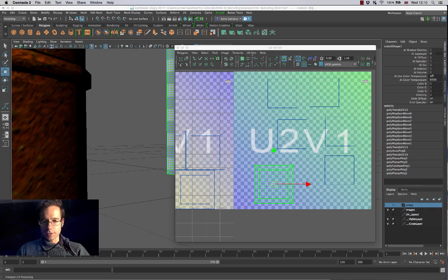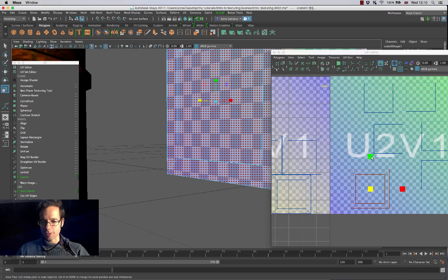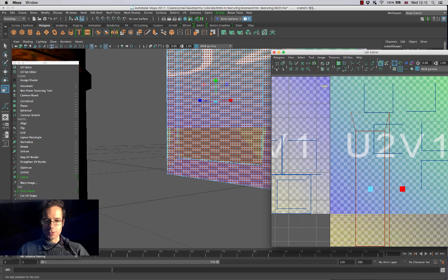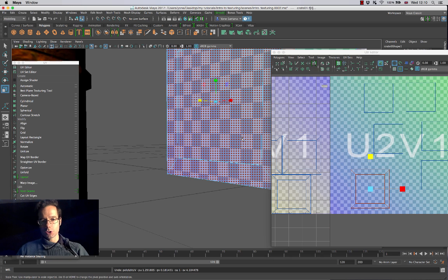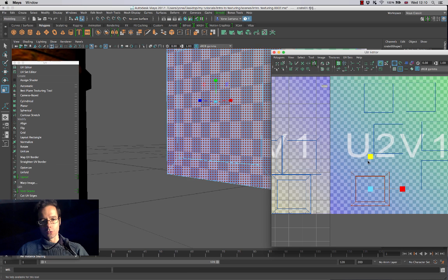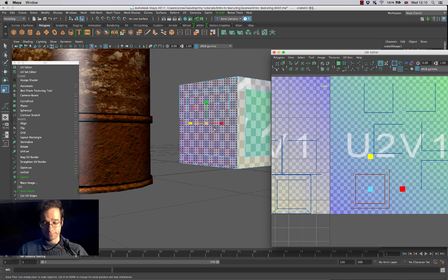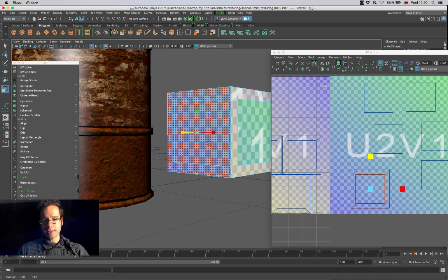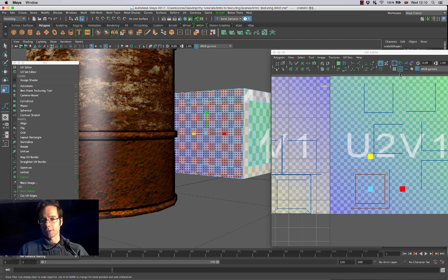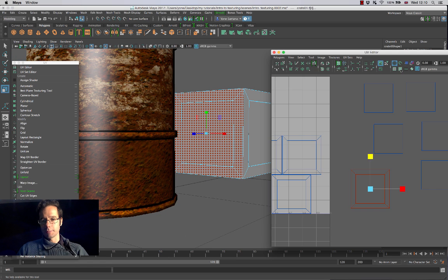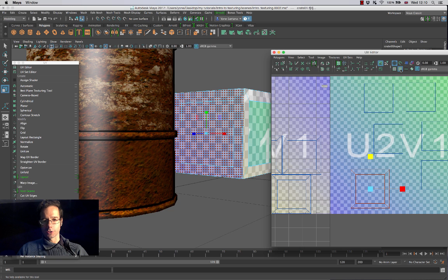If you see UVs that kind of look like this, and I'm just going to do an exaggerated view, where you see that I'm using the scale tool and they all look like little rectangles, that's wrong, and you want to make sure that you're using the scale tools to actually make sure that each one of these faces inside of the cube has a little UV tile that's as square as possible. And that's why we have this little check pattern tool in Maya 2017 over here that I'm turning on and off right now, just to make sure that that is proportionally the right size.